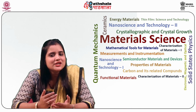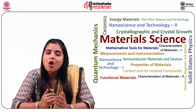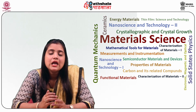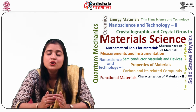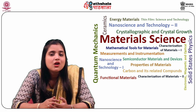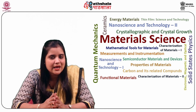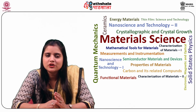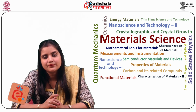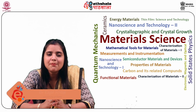So students, let us now summarize what we have learned in this module. In this module, the Hall measurements of thin film samples were discussed. Secondly, electrical resistivity measurement using the Van der Pauw method was explained. Third, contact methods for resistivity studies were discussed. Next, the concept of current voltage and dielectric studies for thin film characterization were discussed. Finally, the capacitance voltage measurement for thin film samples was explained.